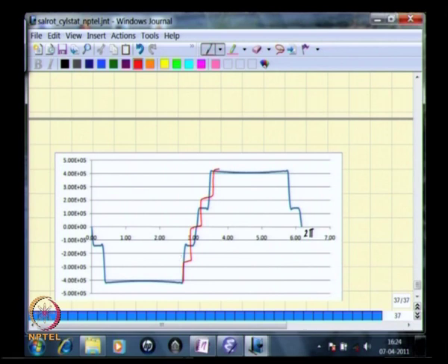therefore one can understand that in the limit where the number of slots is very large and conductors are uniformly distributed around that distribution angle, this H variation would be almost a straight line here, and then this area becomes flat in any case, and then again a straight line variation, another straight line variation here. So the MMF or the H field waveform is trapezoidal.